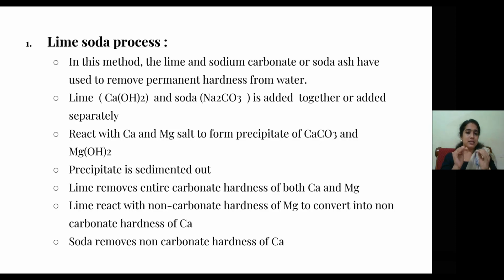The lime is Ca(OH)2 and the soda is Na2CO3. They can be added together or added separately. They will react with the calcium and magnesium salts. That is, the permanent hardness is caused by chlorides and sulfates of calcium and magnesium.